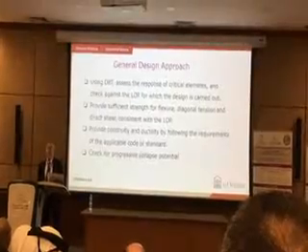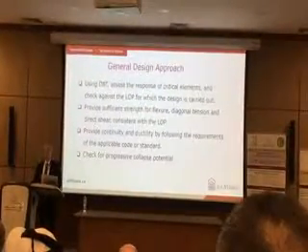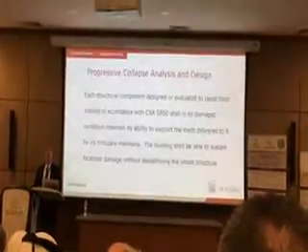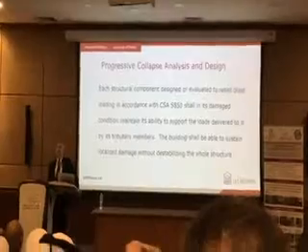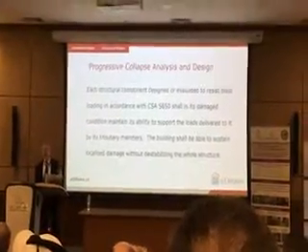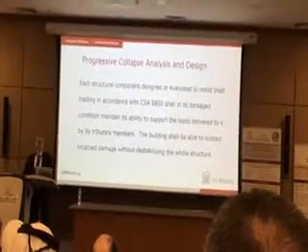And then the last step is, after designing individual members, you now do progressive collapse analysis. Now, progressive collapse analysis is done to make sure that failure of a single element doesn't lead to a whole series of failures.